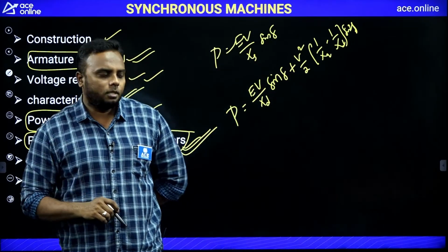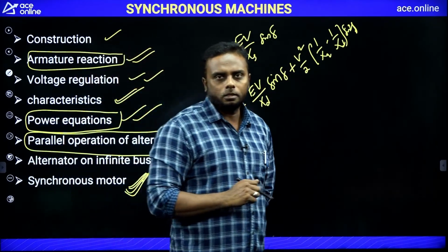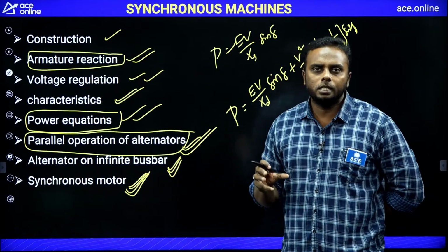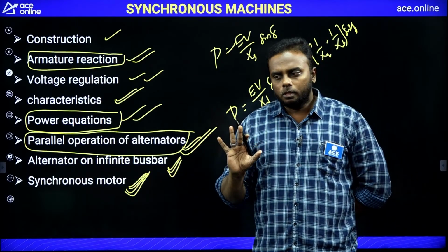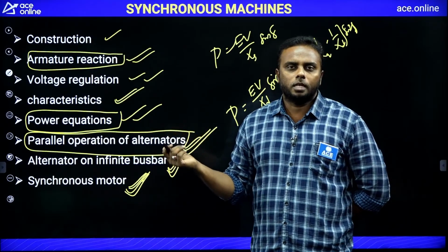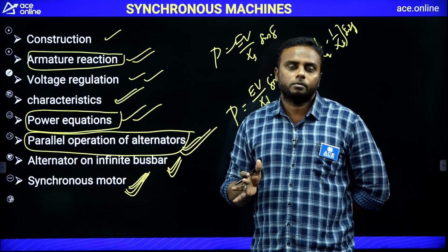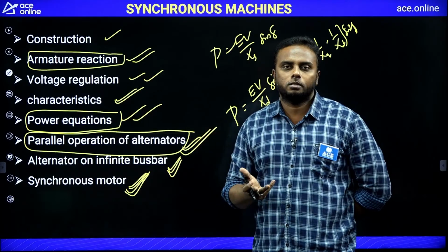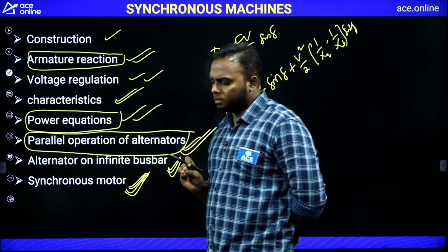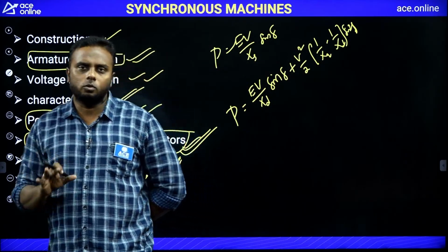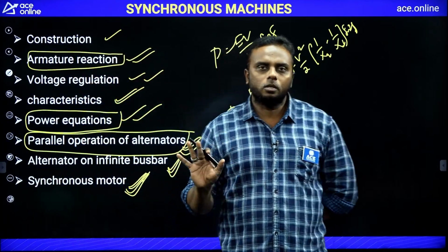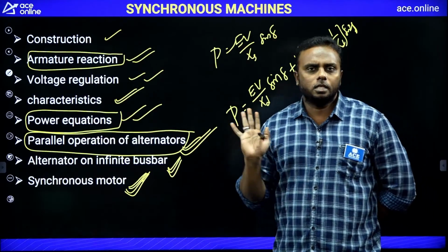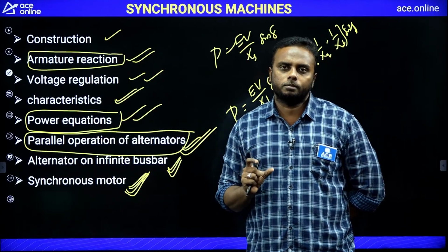But in DC machine, you don't get that many equations. Easily you can remember. That's why DC is a little easier than these topics. There is not much analysis compared to this. At the same time, no phasor diagrams and you don't get any large equations. That's why you can learn DC easily and do calculations also very easily, because there are no reactance terms, no voltage drops due to reactance. Only resistance drop will be there and brush drop will be there.